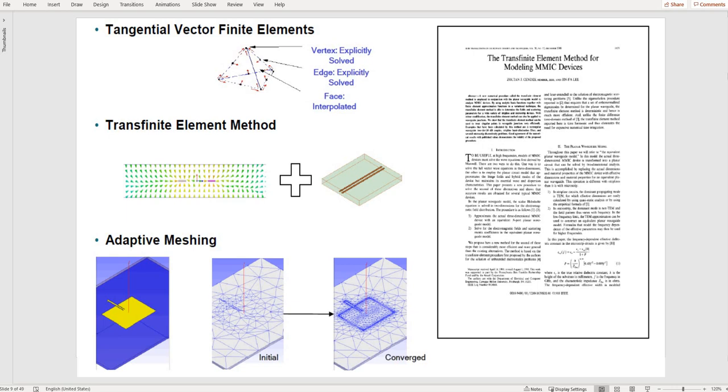As you can see in these figures, in the adaptive meshing process HFSS generates an initial geometrically conformal mesh, and then using the initial mesh, HFSS computes the EM field that exists inside the structure when it is excited at the solution frequency.